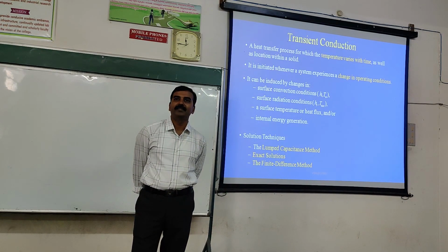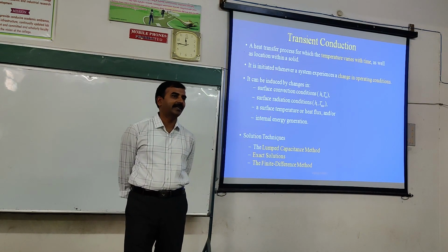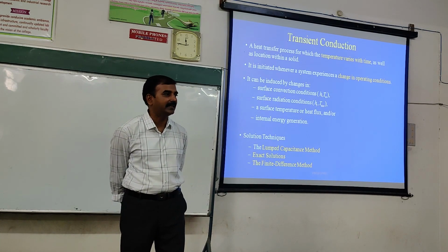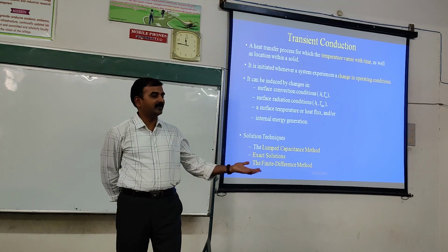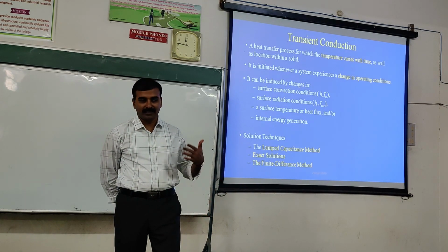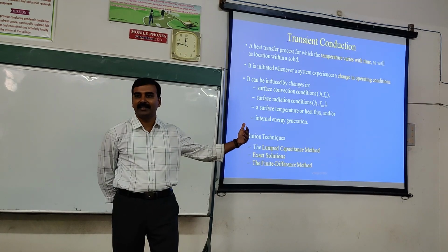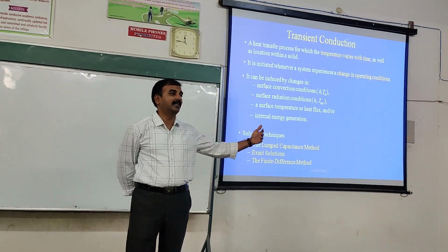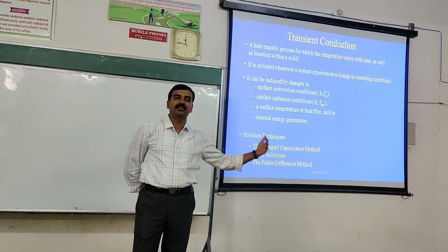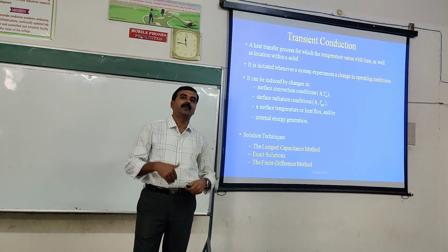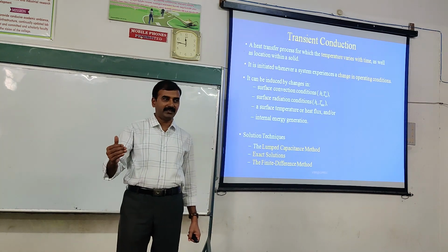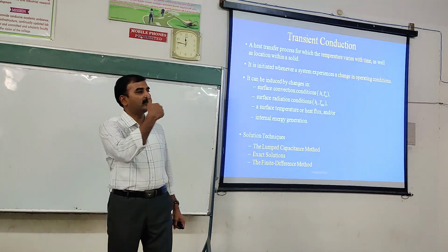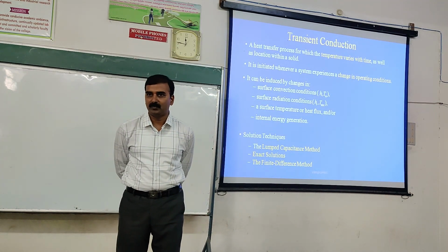With the assumption that the cases are under steady state condition, the right hand side is made 0, and with other assumptions like one dimension, we have neglected gradients in the y and z directions. With the other assumption that there is no internal heat generation, q dot, we solved some problems. But progressively we included q dot at some stage, and now we are including time also.